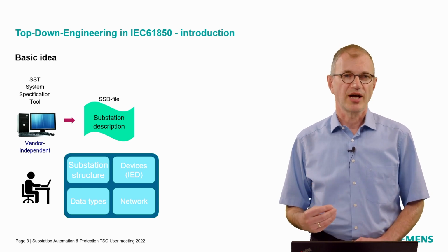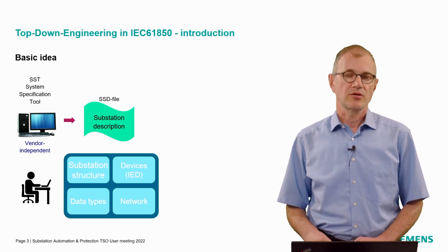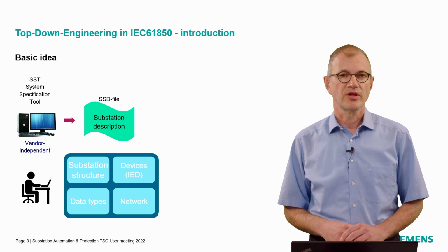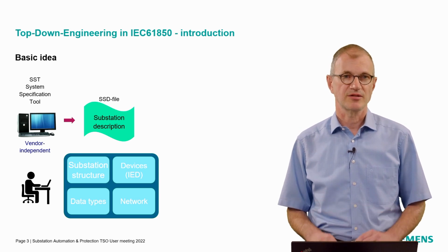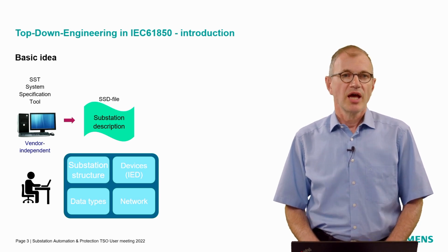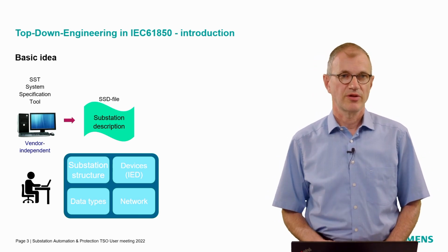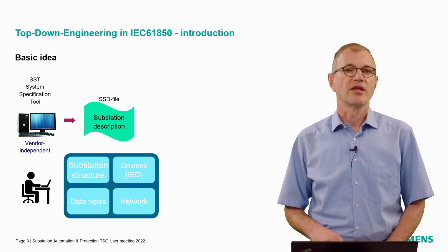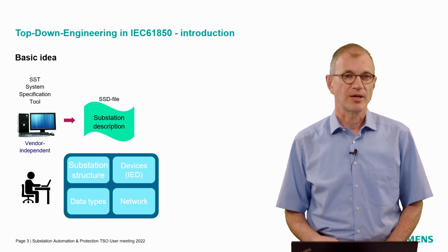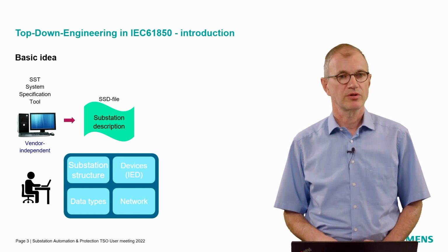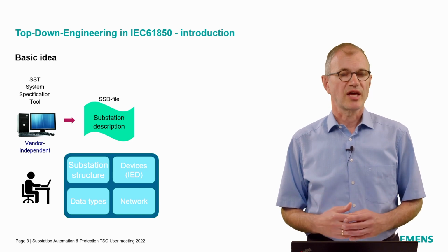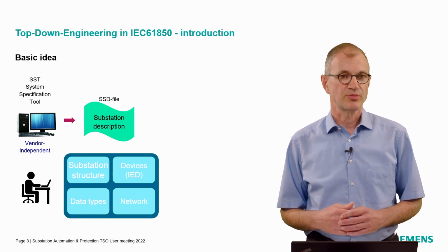It's also defining data models and also including the engineering. This is part 6 of the 61850. The basic idea of this part 6 is that there is a language, a substation configuration language, SCL, which is able to describe a substation.